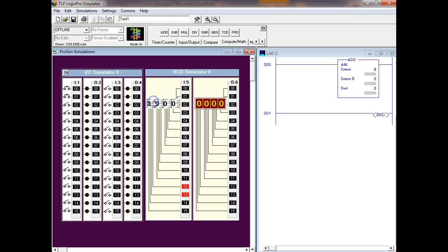So there's 1, 2, 3, 4, 5, 6, 7, 8, 9, and then it doesn't go any further. It's BCD. So if I was going to tell my motor to run at 200 RPM, it's going to give me 200 in BCD, and then I'll probably have to convert that over to what? Binary. Okay, y'all understand that? So that means we've got to have instructions that allow us to go between these different codes.